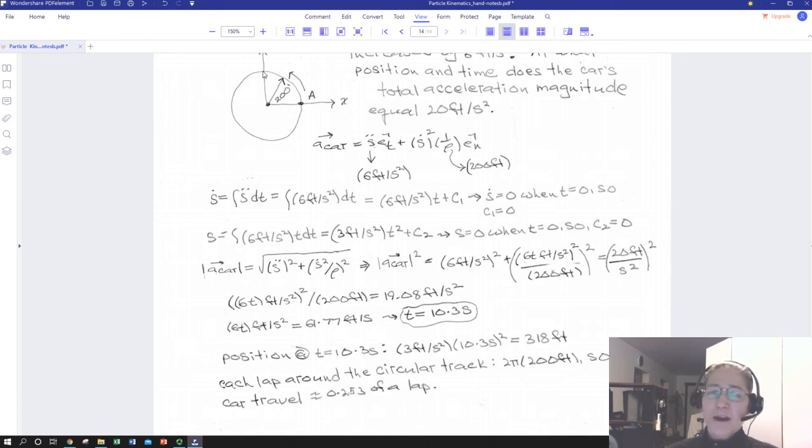Or we would have had to have some point of interest where we knew what the radius of curvature was at that particular point. Otherwise, we couldn't have solved for it. But there's a lot of conditions where we do know what it is. So there's plenty of paths of very practical interest that use a circle. A lot of highways are designed where the horizontal curvature is circular. The vertical curvature is quite often parabolic. But this is a great example of something that is definitely used for things like road design.